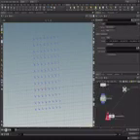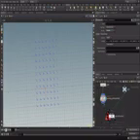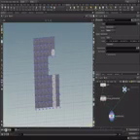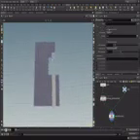Oh, this is set to points. Oops, it needs to be set to prims, of course. There we go. Let's call this prim to centroid. Alright, and this is going to be wired into the Voronoi fracture, which means right now we have subdivided our original polygon and we don't need an interior, so we can remove that. And now we have nice squares.